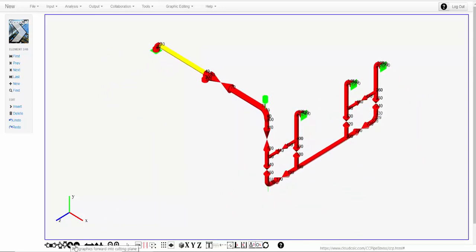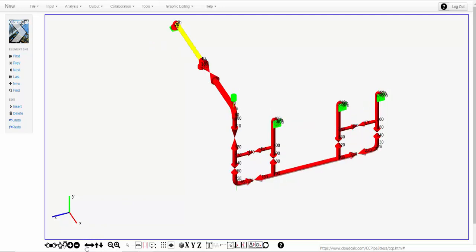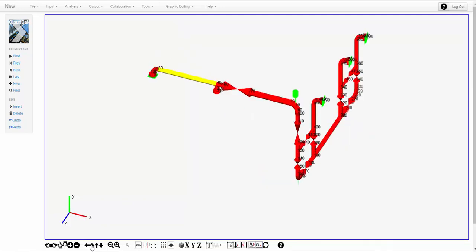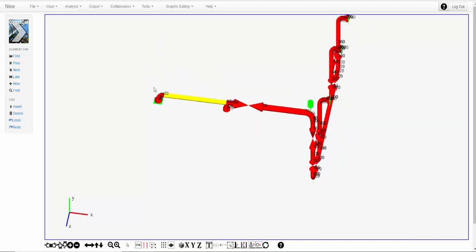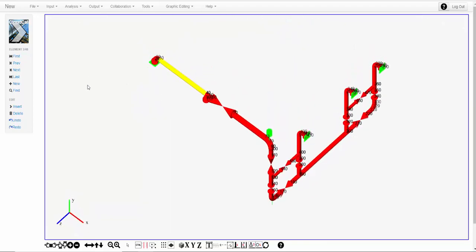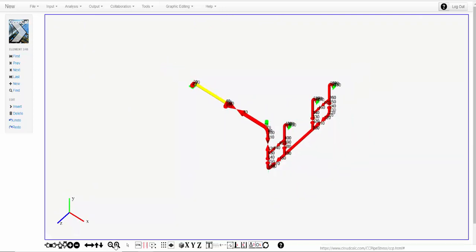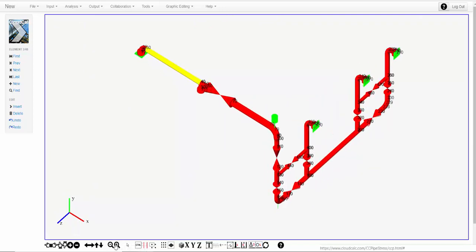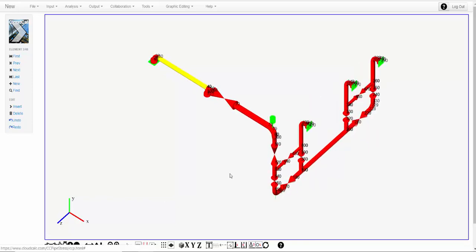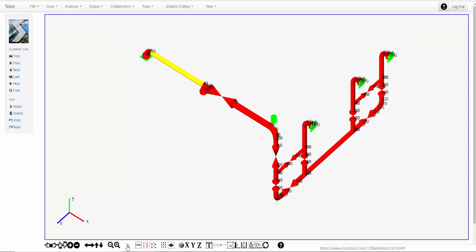This is for moving back and forth through the cutting plane. This is for rotating. So you can click these keys, or you can use the cursor keys up, down, left, right, or you can do a shift left click with the mouse, and it allows you to freely rotate these things. Zooms, okay. Zoom out, zoom in, use the minus key, the plus key, or as I prefer, the mouse wheel. It's the easiest way to go. This puts you in draw mode, so we can say click, let's build a pipe from here to here.